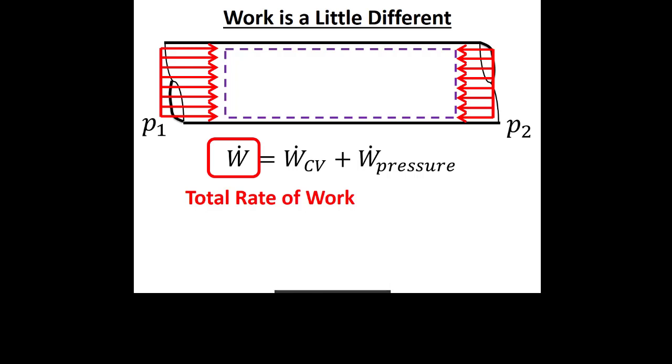Because there's friction where it meets the surface, and that friction robs it of some velocity. But here in a pipe, provided that the areas are the same, and the densities or specific volumes stay the same, I'm not allowed to have friction reduce the velocity of my fluid, right? Because if I did, I would violate conservation of mass.